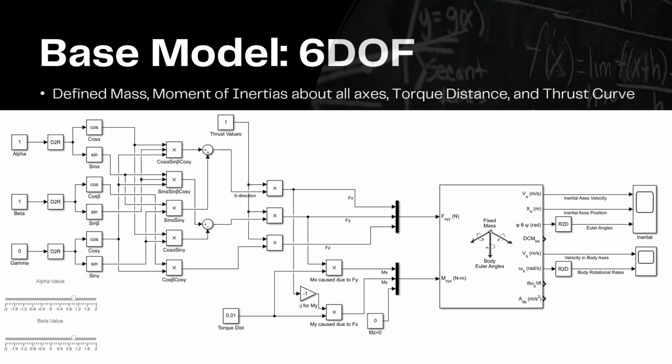In this case, you are supposed to take the values of angles, position, and velocity and use them to change these two angles such that the defined mission can be completed. Also, here you can see that I have applied a constant force as thrust. Later, we will check your model with disturbance forces in different directions and see the results. We'll just add some forces to the forces that you have applied and check if the model is still able to take the rocket through the defined mission.